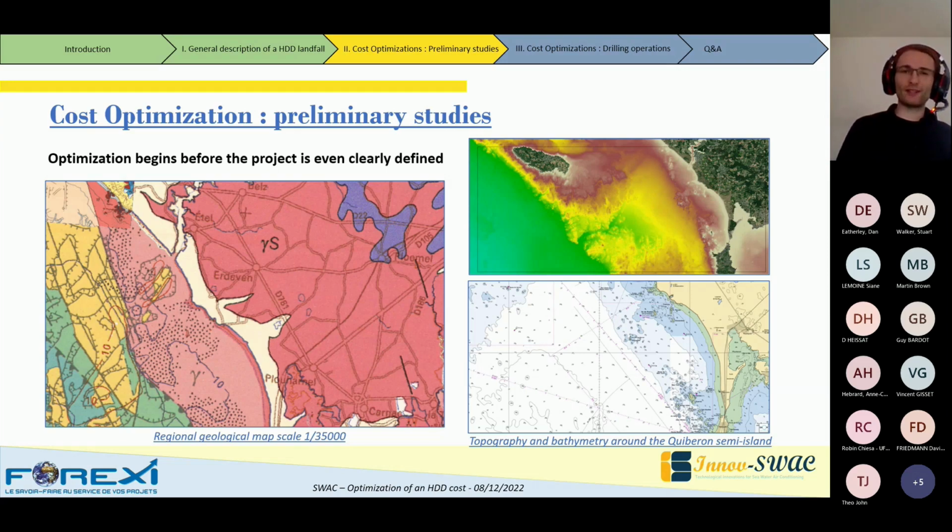Okay, so now, next step of the project, I want to move on to geotechnical survey. I want core samples, I want pressure meter tests, I want CPT. Depending on where you are in Europe, the tests are different. I want lab tests, and I want to figure out what the soil actually looks like. But, you know, we have a bit of a problem.